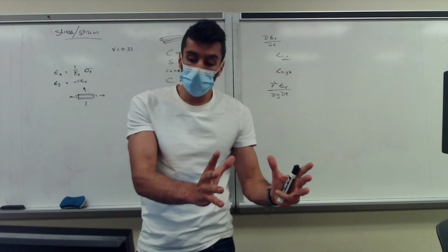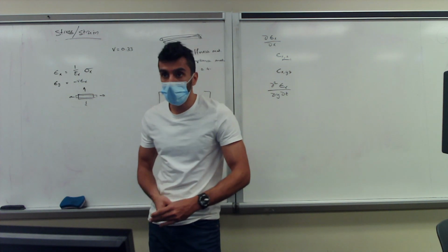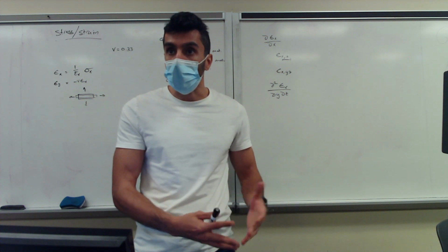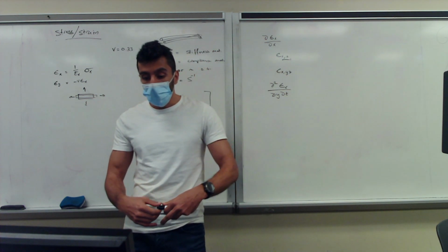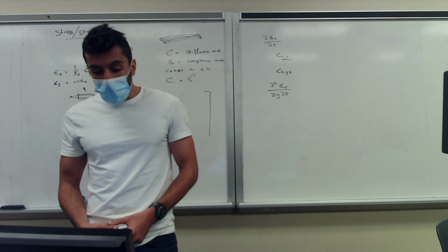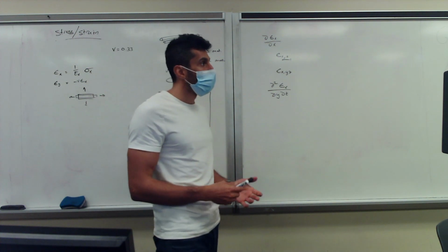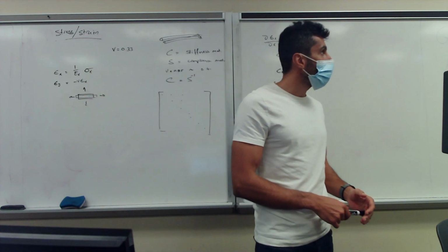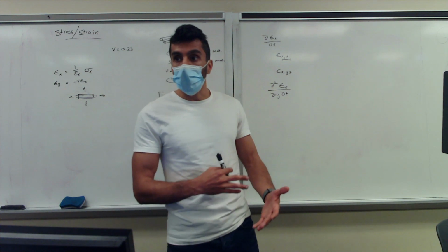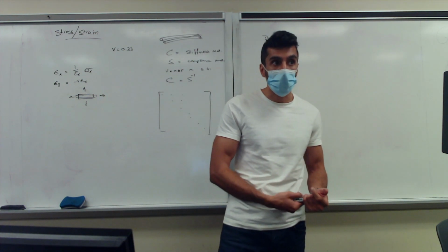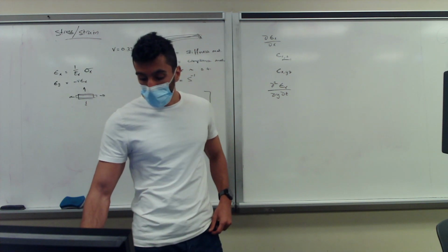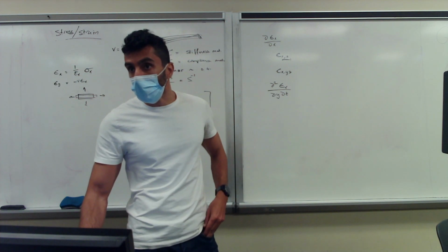Then we can look at the third order derivatives. Well, we have some third order derivatives and we have some second order derivatives. If we do the full extent of the equations, we know that our third order derivatives basically cancel out. We can eliminate them, remaining with 6 equations, which are our compatibility equations. So what this basically means is, if we have a solution field of x, y, and z for a given strain, these equations must be satisfied in order for our solution to be a valid solution. If they're not satisfied, then we have a problem. Then basically a solution does not work, or your proposed displacement field does not yield the correct strains.